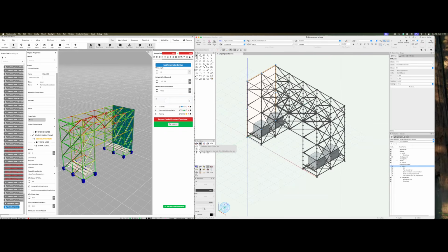Well, I was also curious, what if that material allowed wind to pass through? What if it was a mesh? Okay, the main problem with this, and we have these questions quite often, is that when you look at normal planes or stuff like this, they don't really give you a value how much wind is passing by. So if you don't have a specific value by the manufacturer, you are forced to assume that this plane basically is wind transmissible.